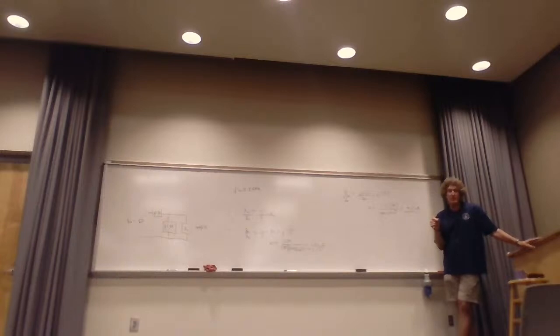a variable value for a capacitor or inductor, use it. That way you can tune it. Because even when you put the whole thing together, the stray inductances and capacitance can change that frequency. So you usually give yourself a little breathing room so you have a little bit of a tuner. You all see these little pots? They're usually square. They look like a cube, and they have an adjustable screw on top for variable capacitors. And you want that. You always want breathing room,